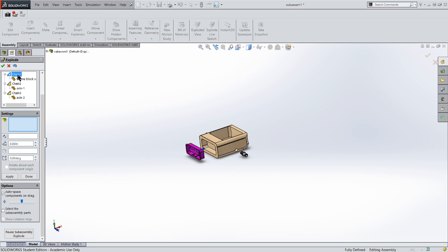If I want to edit each one of these chains, all I do is right click on it and I edit the step, and now I get the distances. So let's say I wanted to move them all at 1.5 inches. I could certainly do that, and I would right click and edit the step, and I would make them all 1.5. So now when I come back down and I look at all these chains that I go through, they're all the same.